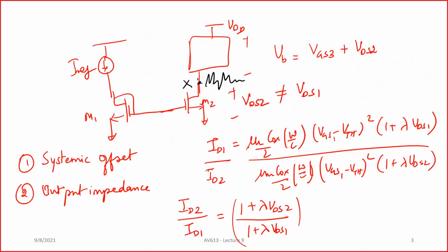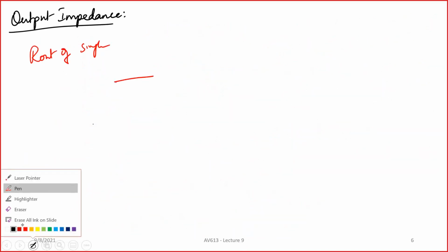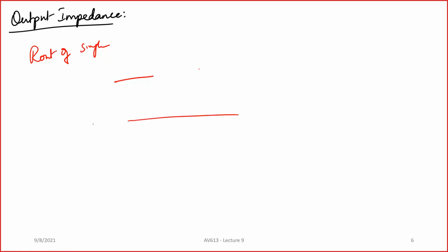So in other words, you have some small signal variation here, a voltage. So this current ID, what is the small signal variation? For that, you take the help of the small signal model that we have derived. Since we are looking at DC type quantity, low frequency signals, we only look at the low frequency model of your MOSFET. So this is your gate terminal, this is an open thing, this is your VGS, let's say this is your S, this is your D, and this is gm times VGS, and this is r0.